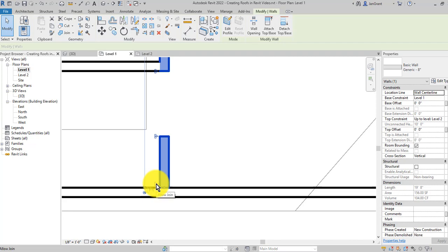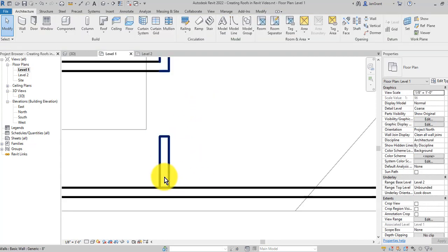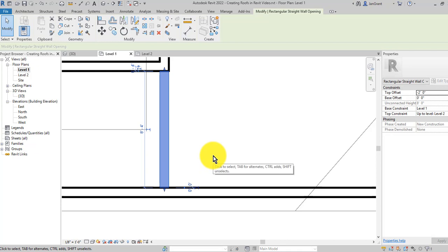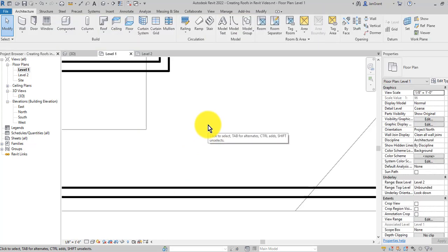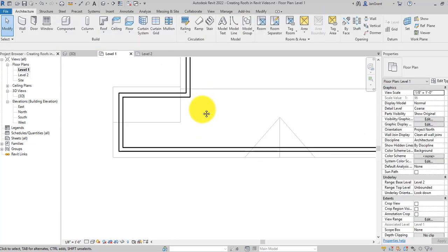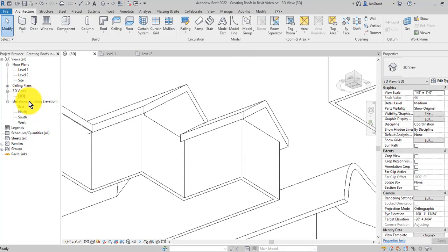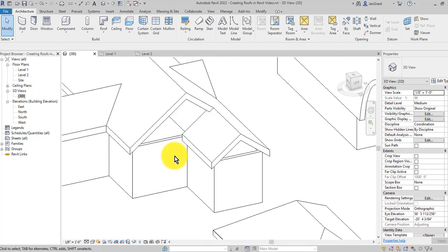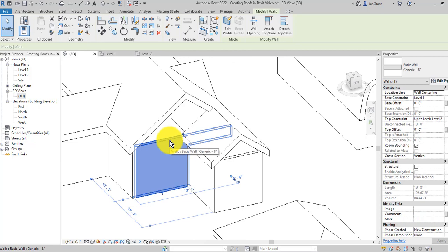So that's another thing that we've picked up that's about walls, but it does pertain to this, because now that this is not joined, I can go back to my wall opening and pull it all the way down and not get an error, because now it's disconnected from the other wall, and there's my nice opening. But the point of all of this going back is to be able to maintain it so that now I can click on this wall.